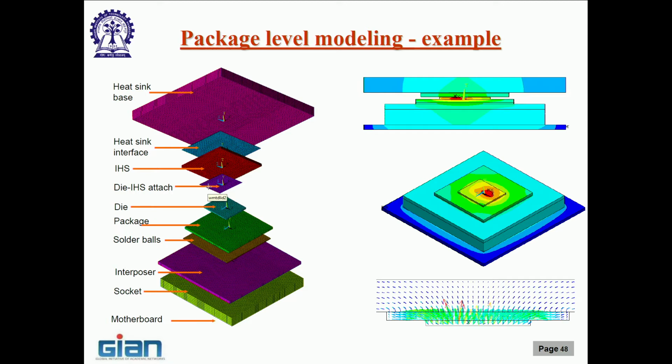Okay. If I have to mesh the 50 microns with at least 2 elements, then 25 microns is my mesh size in the vertical direction. It is killing. Okay. I do not want that. So, a trick that is often used, with of course some penalty in terms of accuracy, is